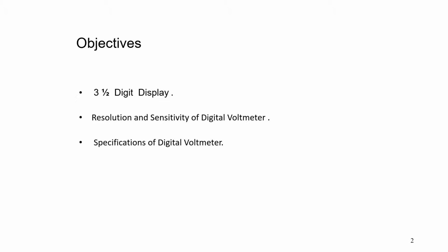The ramp voltage is continuously compared with the voltage that is being measured. At the instant the two voltages become equal, a coincidence circuit generates a pulse which opens a gate. That is, the input comparator generates a start pulse.